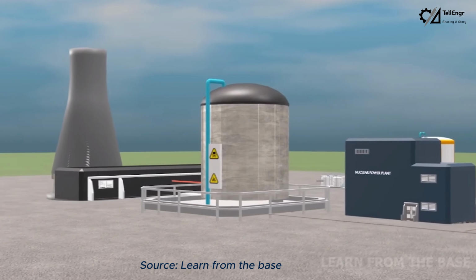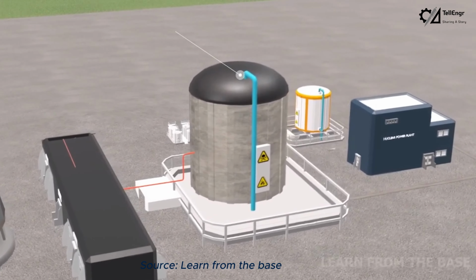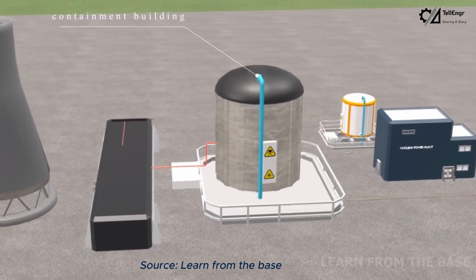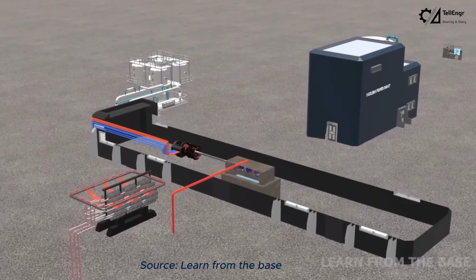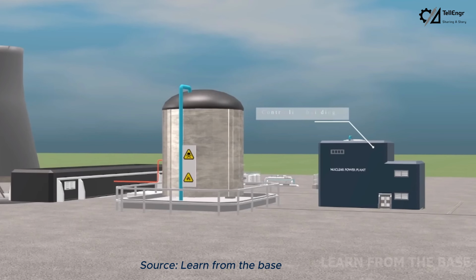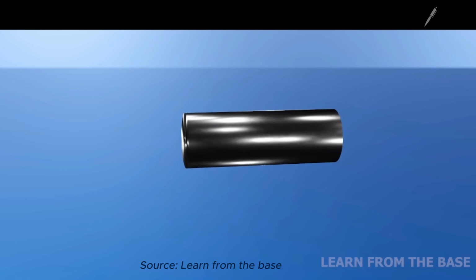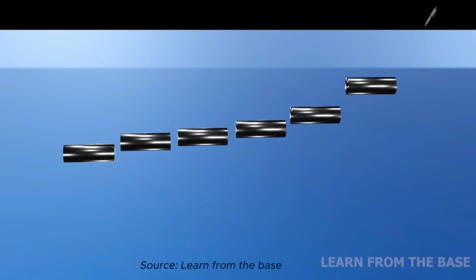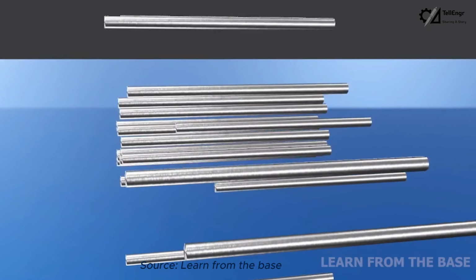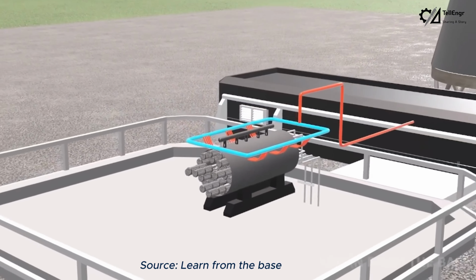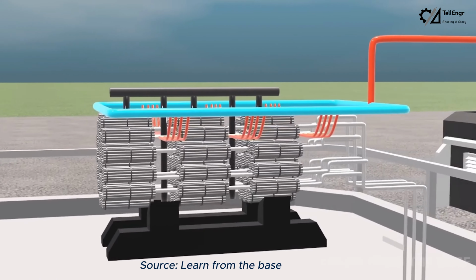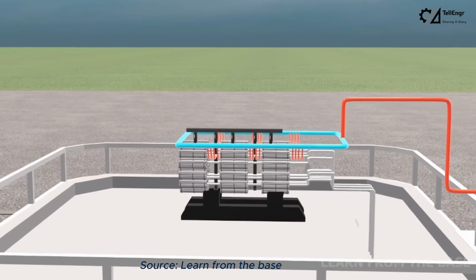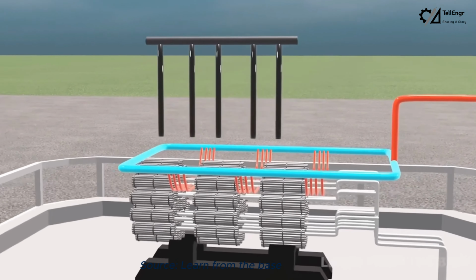In nuclear reactors, the transition from liquid to vapor, characterized by the onset of boiling, leads to complex flow patterns. For example, as subcooled water enters a vertical tube subject to constant heat flux, bubbles start forming, coalescing into liquid slugs, and eventually transitioning to annular flows. These flow patterns have critical implications for reactor safety and efficiency. By studying these patterns using flow maps, engineers can better understand heat transfer processes, predict critical points like dryouts, and ultimately ensure the safety and optimal performance of industrial systems.